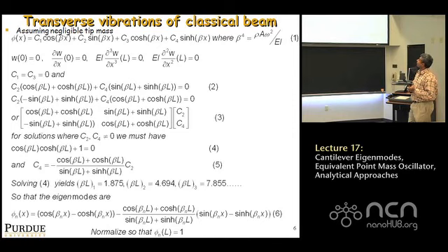So on the right-hand side, we neglect tip mass. As I said, this is an approximation. There are issues with this. But let's neglect it, which means that the shear force and bending moment need to be 0 at the free end. All right?